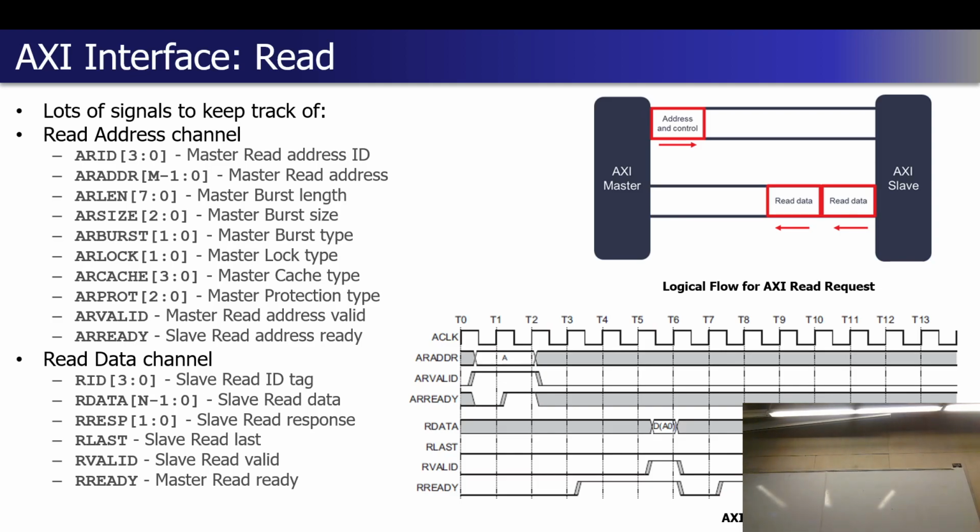It has to determine at some point that, yes, I am now ready to do a read request on an AXI bus. That's never shown here. That's always separate logic that then is going to connect to this logic that you would have to create to interface with the AXI bus. But you have to assume that to start a transaction, there's a valid desire to read some data from some location in your memory. That's a given, but someone does have to generate that logic at some point.